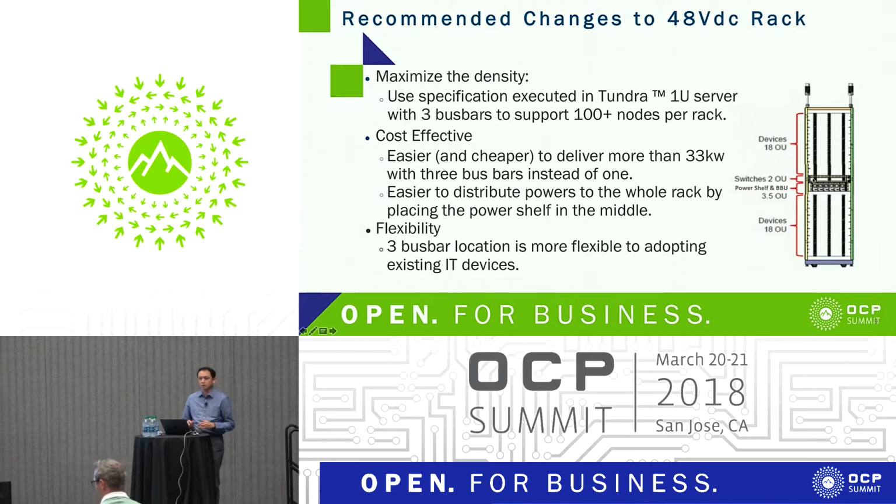It is from electricity distribution's point of view. You have a whole rack to distribute the power to, and you need to make sure the power delivery to the far end is still enough. Putting the power shelf near the middle is the most logical way. Otherwise, for the bus bar design you might need more copper, or the transmission rate needs to be better.